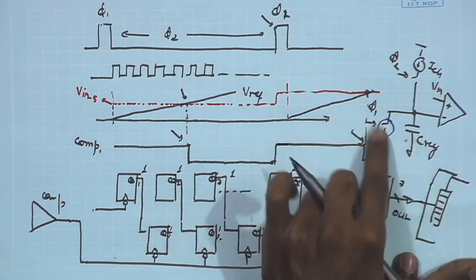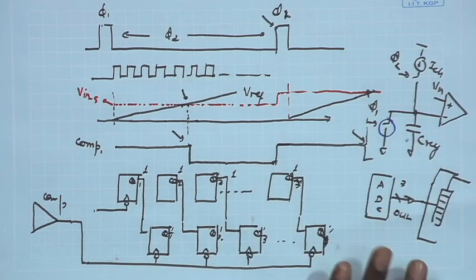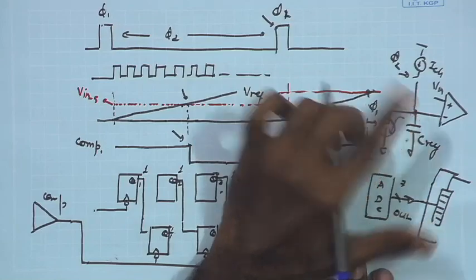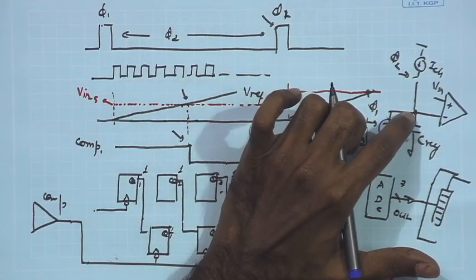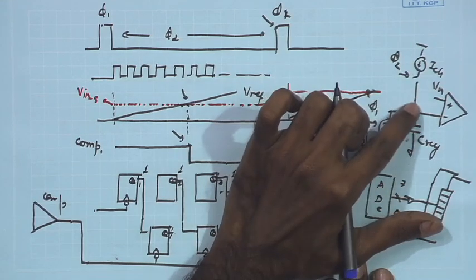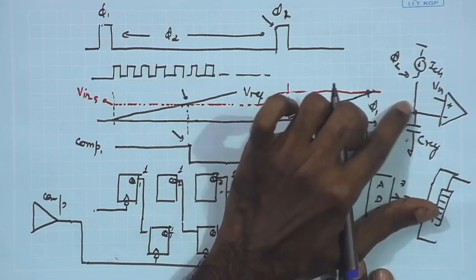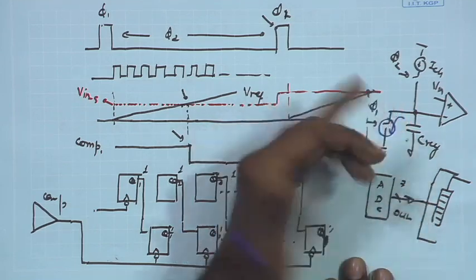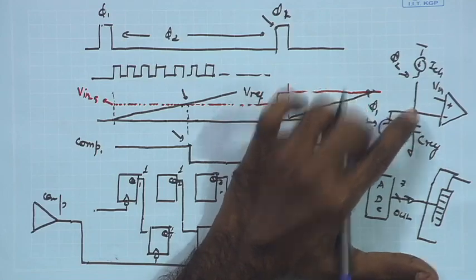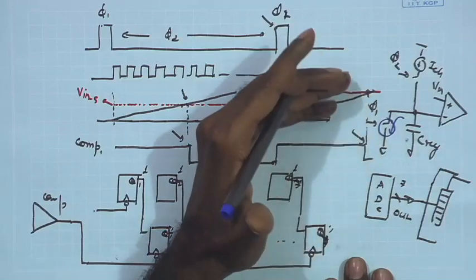So all you need to do is make this switch large enough. Here of course, when we make the switch large, we know that we are going to have leakage flowing through the switch, and the leakage component can once again disturb the stored charge, but this is not a floating node. You are having the current coming over here, and even if you make this sufficiently large, during the off phase we are having some leakage component over here, and that leakage component also will vary as this voltage is changing.